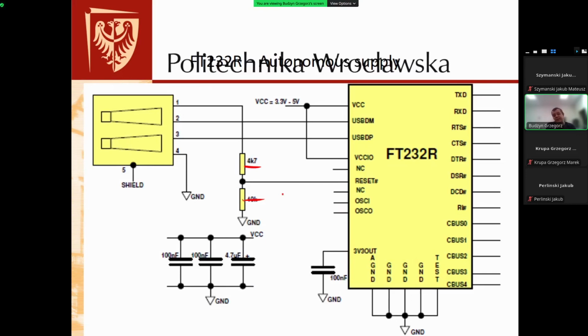The reason for this is that unless you have a battery operated device, normally if you unplug the power supply from your PCB, then this voltage will disappear. Then those lines will go to zero, in fact high impedance.